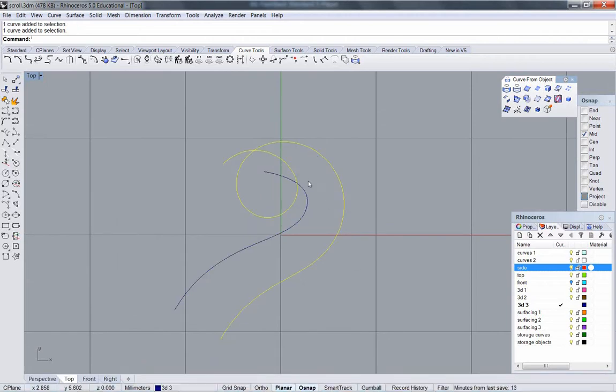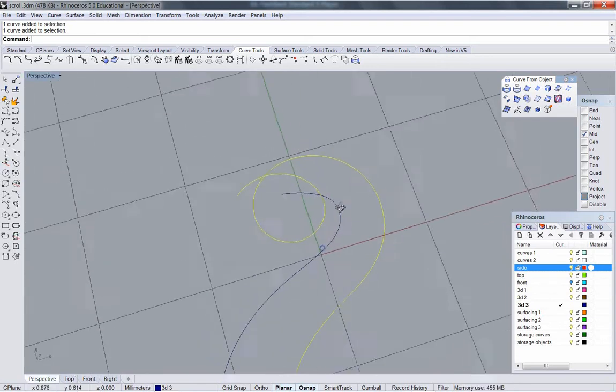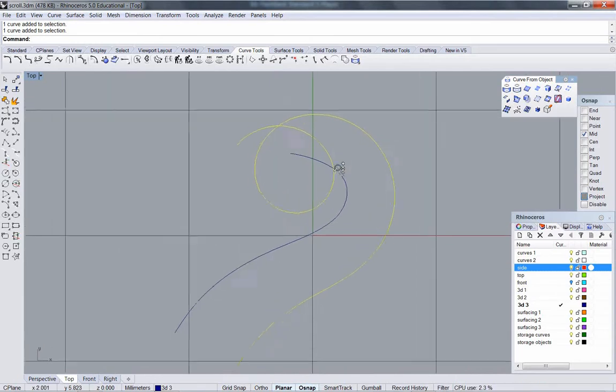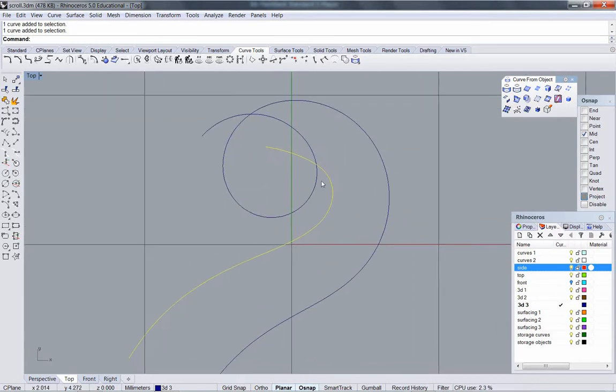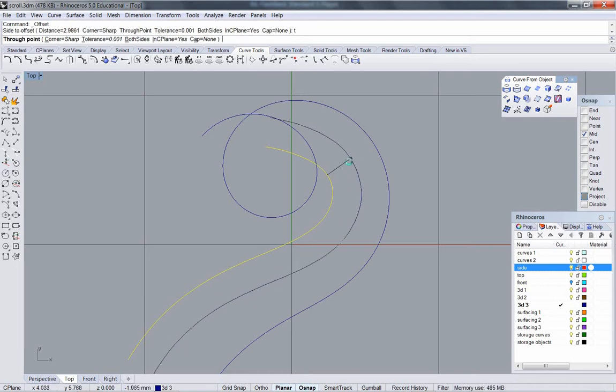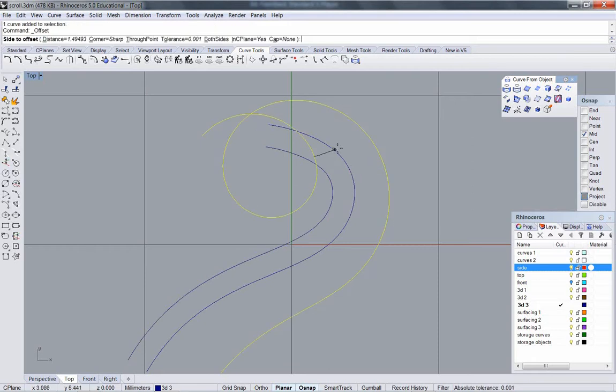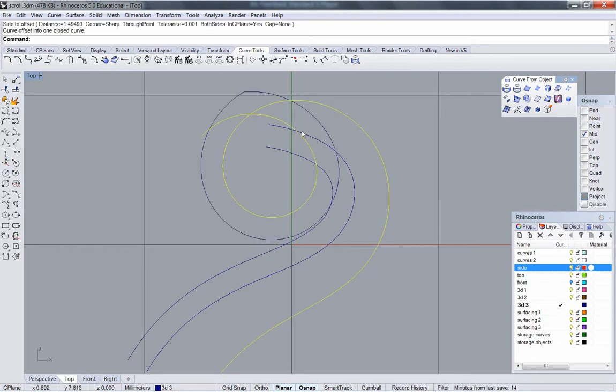Okay. Now I'm going to create this using fillets. I'm going to extrude a block of material and then use fillets to actually create my scroll. I'm going to use offset curves to strategize, to plan those fillets. What's important is that I get as much of a roundness to the sides of this as I can, but at the same time that I leave a central valley of material.